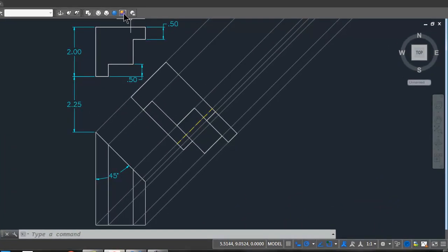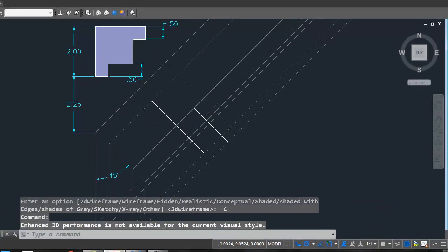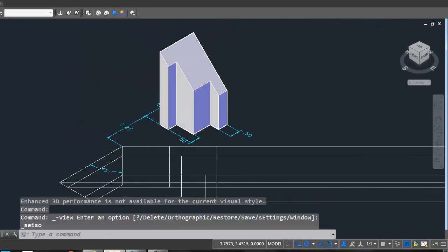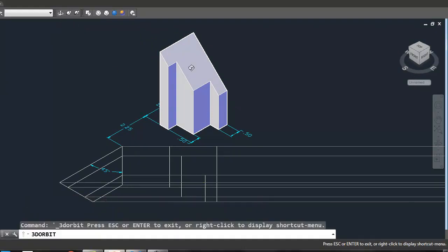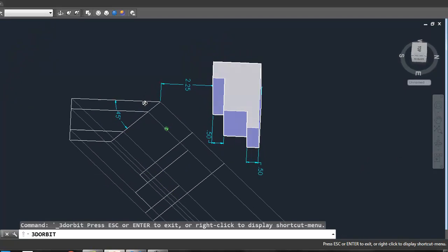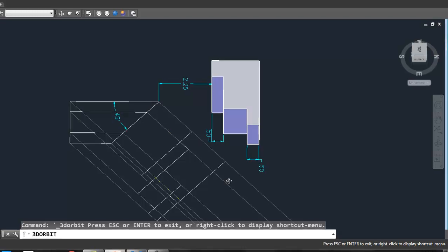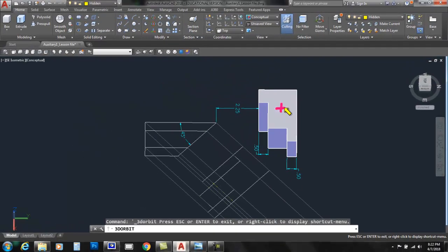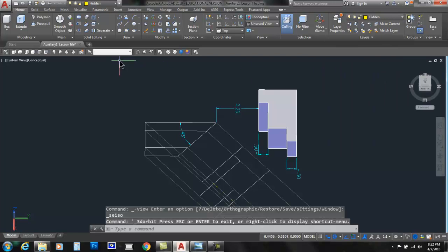Okay, so what I'm going to do is turn on a shading and switch our viewpoint. Now this is 3D, and we're going to get to this in time. So now when I change my viewpoint to be looking directly in at that surface, okay, so my line of sight is looking right in at that surface. Look at what we see. Okay, we see our auxiliary view. So this is literally looking at a three-dimensional object from that viewpoint to confirm that that would be the correct view. Alright, so I'm going to go back to my top view.